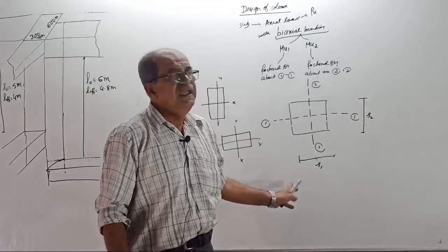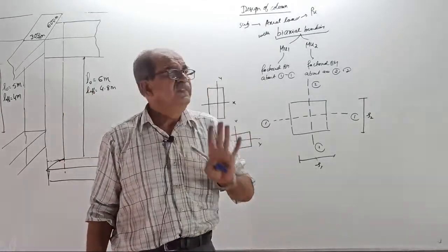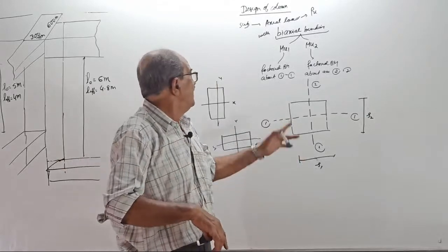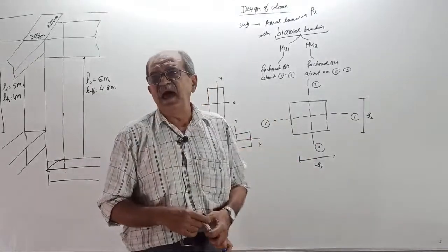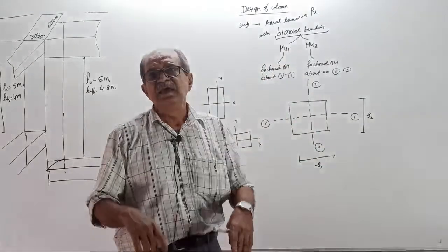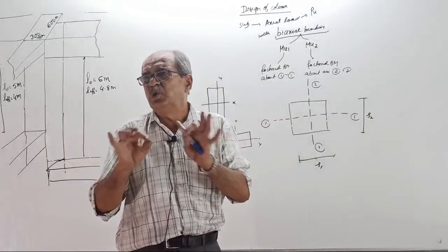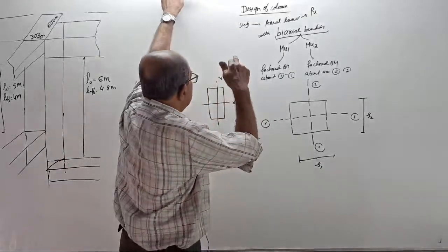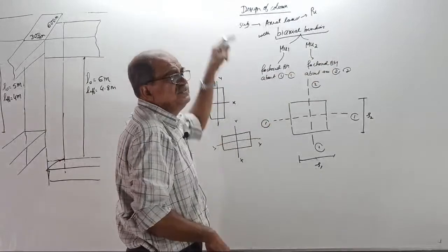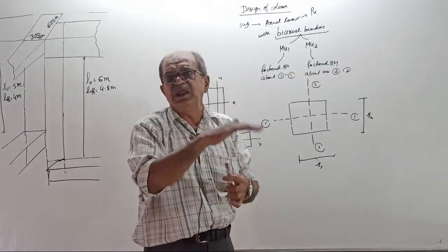Over. E-tabs will tell you the steel required. All the repeated trial and error, interaction diagrams, the combined action, everything E-tabs will take care of. You don't have to worry. Design. Over. That's all. Click design without even bothering what the axial load is.